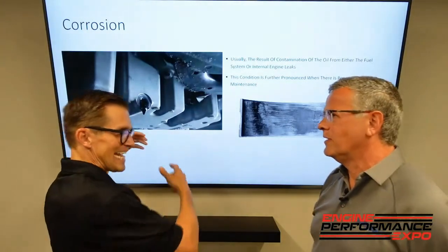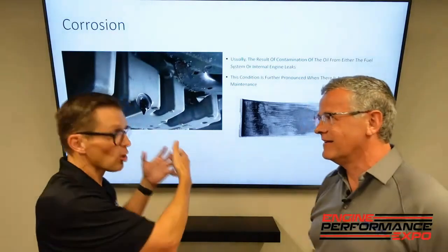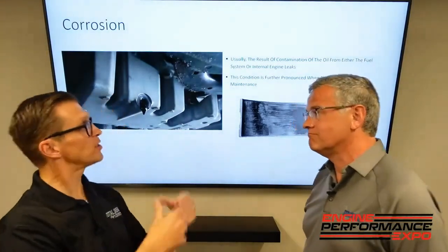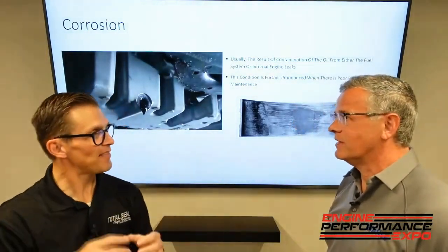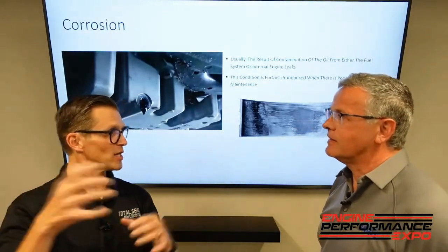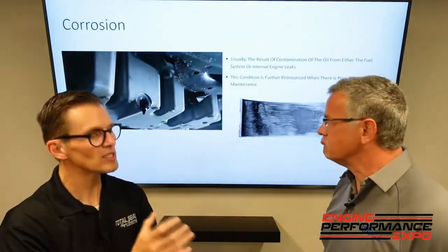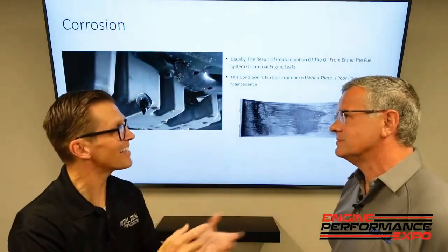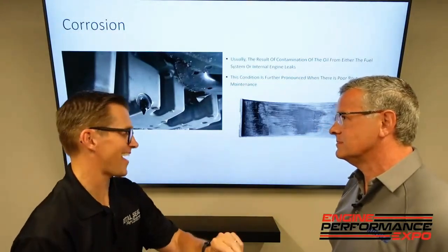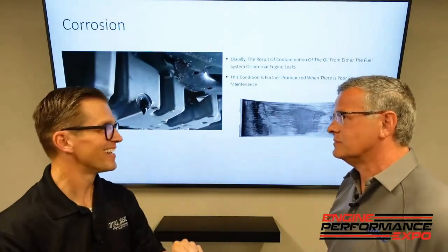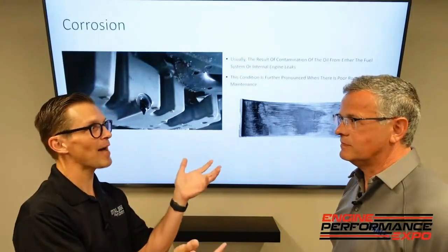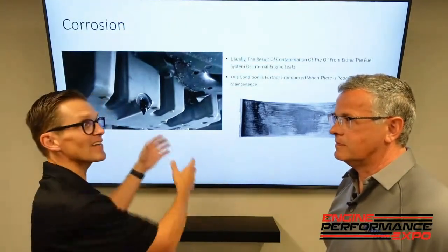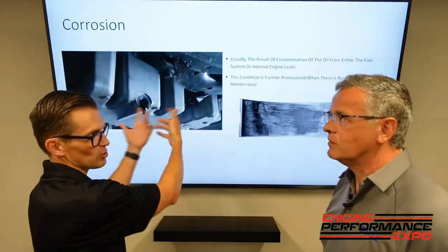So what would eat your engine alive was the sulfuric acid. They created detergent additives that had this overbase to them that could neutralize the strong acids. So what TBN as a test does is take hydrochloric acid, another strong acid, and neutralize the oil to see how much alkalinity is left in the oil to neutralize those strong acids.